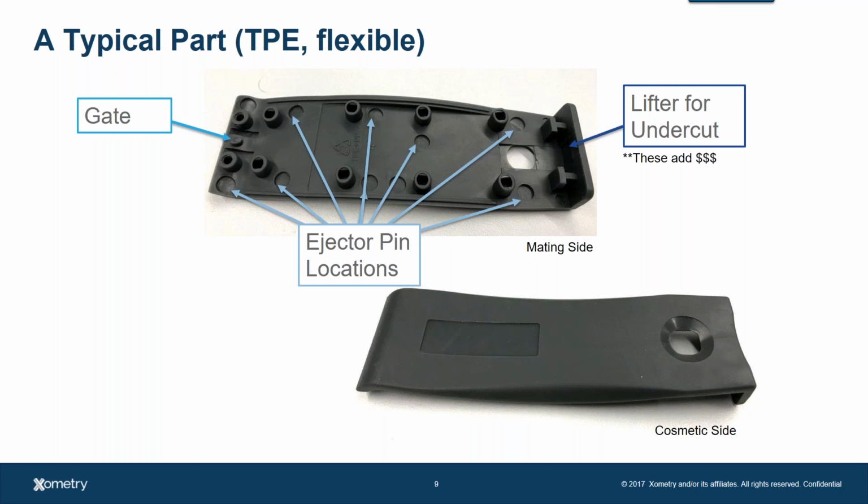And usually you're using a closer clip, and you're just doing a very light sanding on this. So gates are, on most commoditized plastic pieces, where you'll be able to find them. And it's always interesting to me to see where the flow started for that part, because it does indicate how the other side may look by how the material stitches together, especially the more complex a part gets.